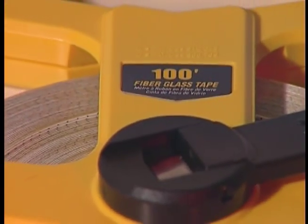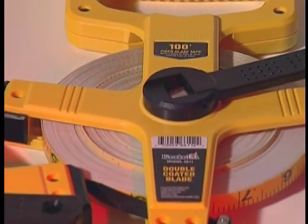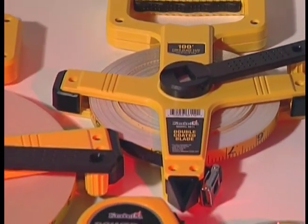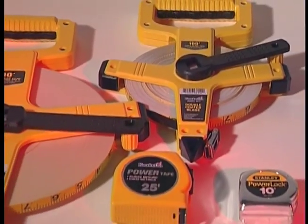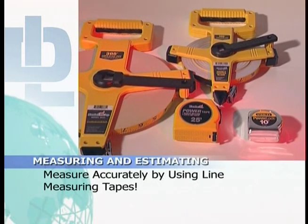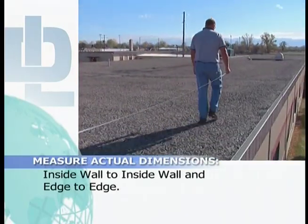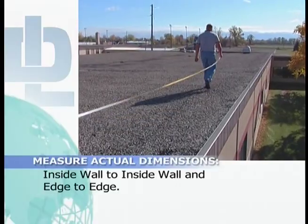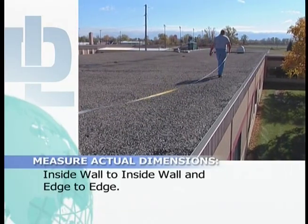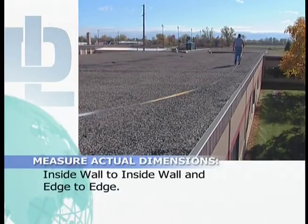As mentioned earlier, bring a measuring tape, minimum 100-foot length, although a 300-foot tape can be helpful on large projects. Bring a 12 to 25-foot measuring tape as well. Other measuring tools are available, but the most accurate way to measure a job is by physically measuring using line measuring tapes. Measure and record all of the roof's actual dimensions, noting inside wall to inside wall and edge to edge dimensions. All additions for field seams and overlaps will be added later.